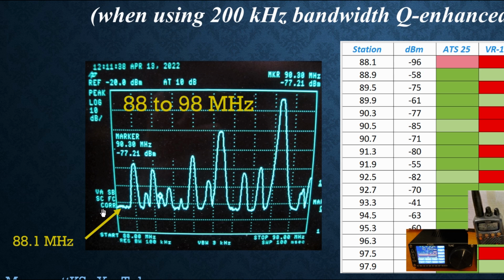That is close to, within about 10 or 20 dB of the theoretical noise floor for an FM broadcast receiver. But in the presence of all these strong interferers, you can't receive it with most radios these days. Even the spectrum analyzer. We'll go into in this video series why the spectrum analyzer couldn't really show that signal,